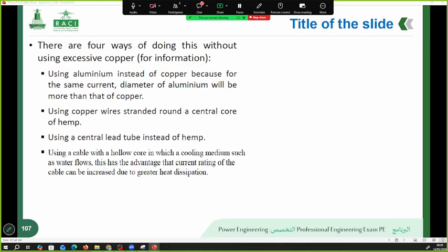For higher voltage cables, in contrast, the theoretical formula yields a very large conductor diameter to minimize the stress. This diameter is often much larger than what is needed for current carrying capacity alone. Therefore, it is advantageous to increase the conductor diameter to this value.